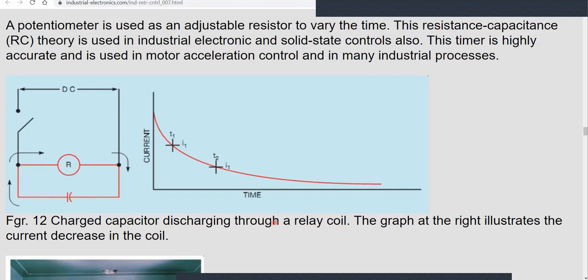So there are many different ways, but this is one way, right? When the trigger is closed, power goes in here, right? That will energize the coil and also charge the capacitor. But when the switch opens, the stored energy will be released or discharged from the capacitor through the coil. So that will keep the timer going, right, with the off delay. So this is one of the solutions, all right?